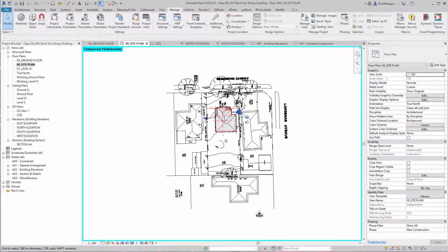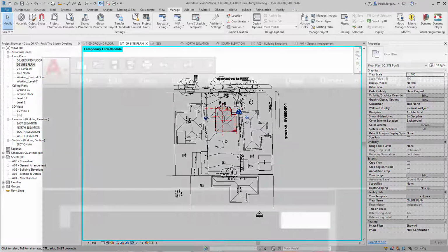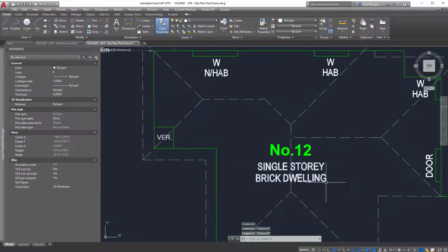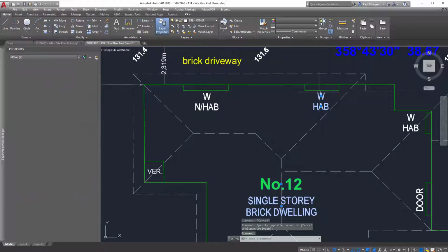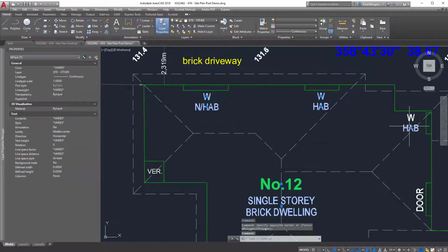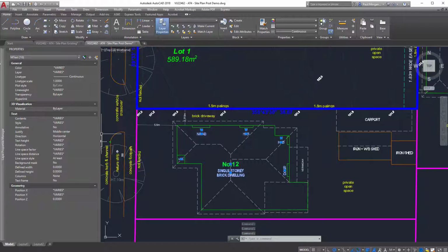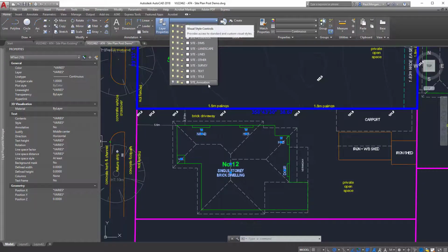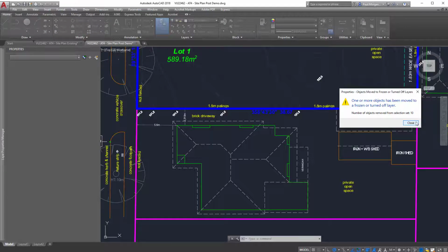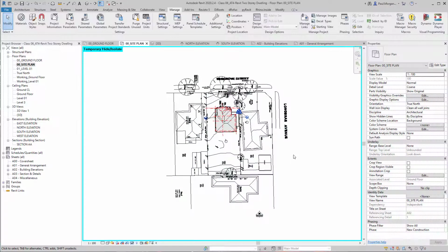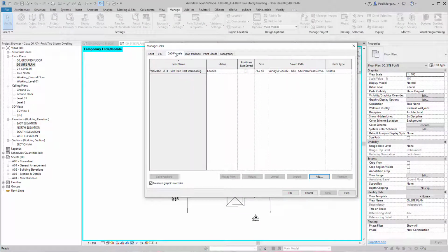And then when we go back to CAD, we'll make a quick change. So let's say for instance that this text here, because I want to add this later on or something, I'll put this on that new annotation layer created, which then hides it. Yep, turned off layer, that's fine. Save that file, go back to Revit, open up my manage links, click on the CAD file, reload.